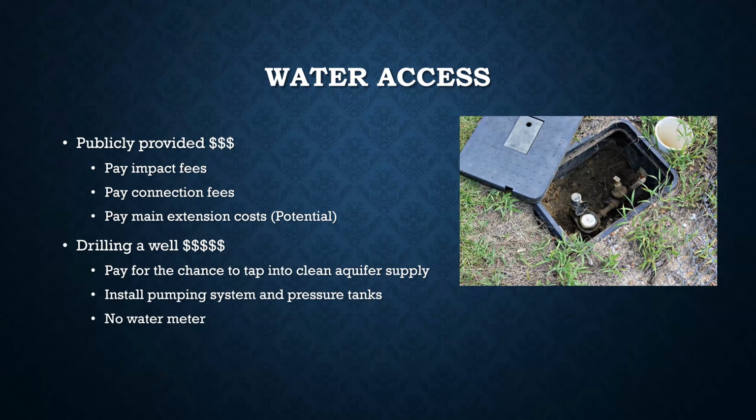But in the case that you don't have that water meter, you're going to have to pay to have the main tapped. And basically what they do is they unbury the main, and they saddle onto it, and they drill a hole in it, and they connect into it and seal to that. They don't modify the pipe in some way. They just basically latch onto it like a leech and pull water that way. So that is how you connect to the main. Sometimes you've got to pay for that, and that would cost more.